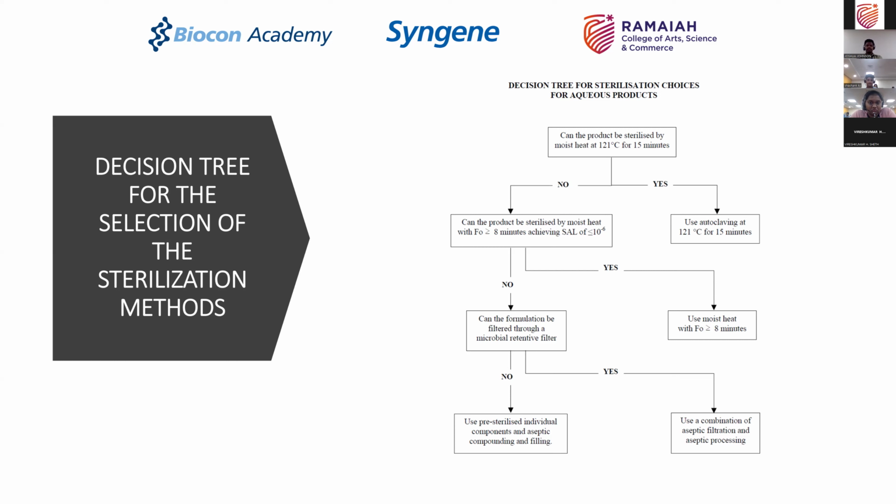And you enter into the third tank, and once you enter into the third tank, then there is no filtration possible. So right from that third tank onwards, till you fill it into the container, which is a vial or a cartridge or a PFS, you are not going to be able to use any filtration, and therefore everything has to be sterilized, autoclaved, in situ sterilized, autoclaved. Use single use components, use S2S connectors, whatever, but you have to maintain sterility assurance at each and every unit